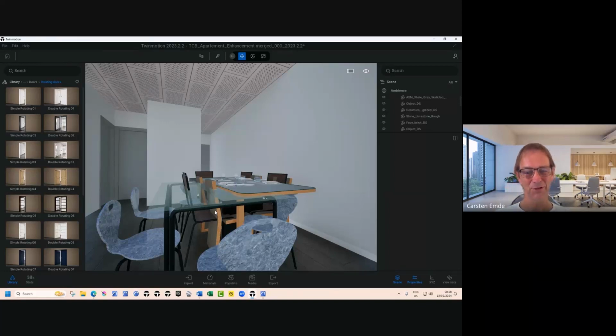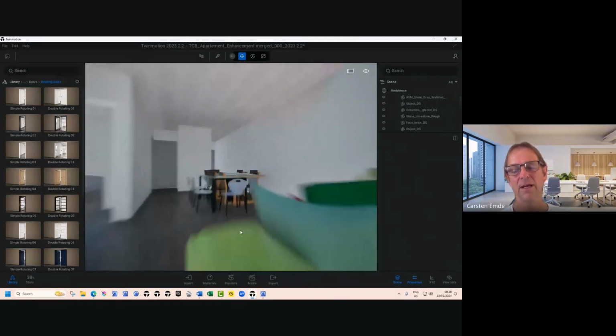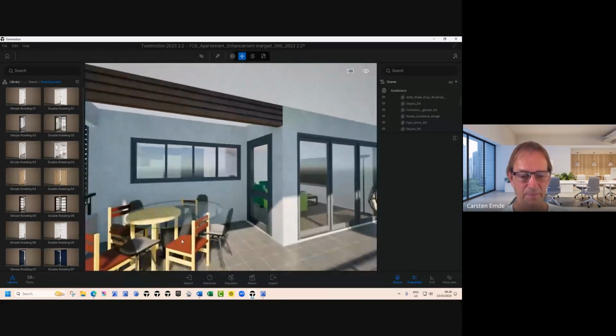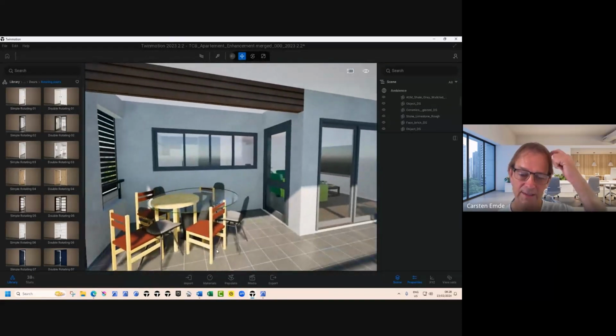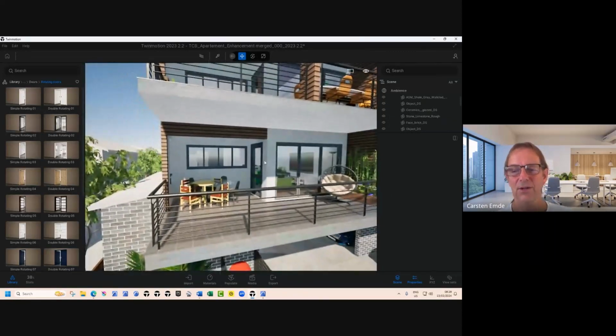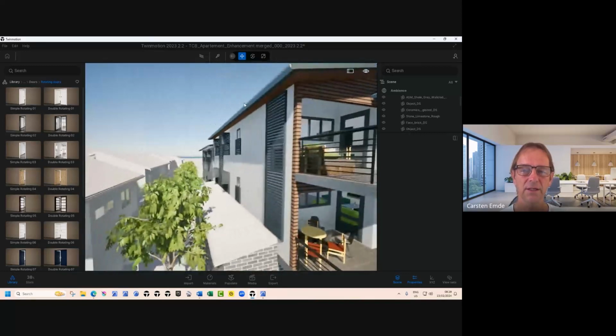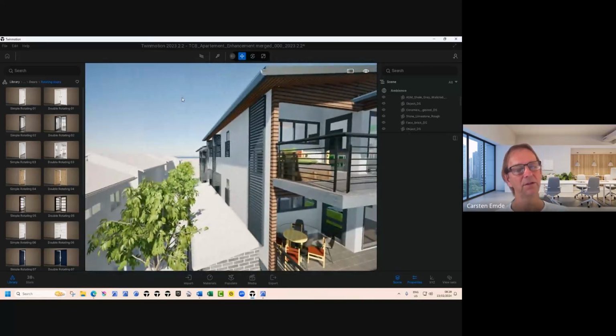The other thing you've got to be careful about is if you do use all the furniture, make sure the material split up is correct, because I've done it before when I use them even as placeholders or when I'm further away, and I apply a material to, as an example, the legs of my chair. I change them quickly in Twinmotion, and suddenly that material is, I don't know, maybe on the side of the balcony or on a piece of facade, because you haven't been careful in the CAD system.